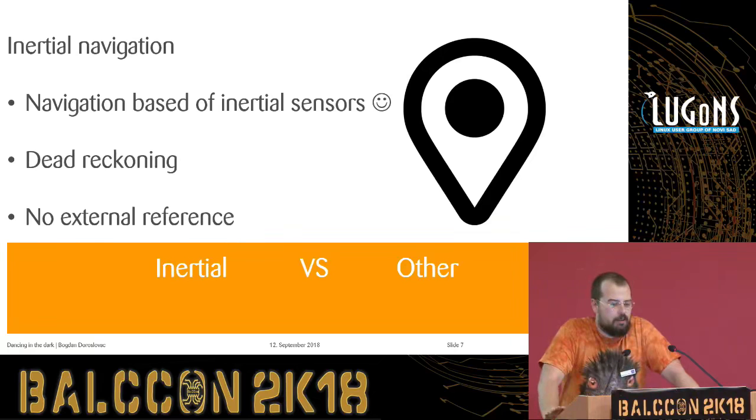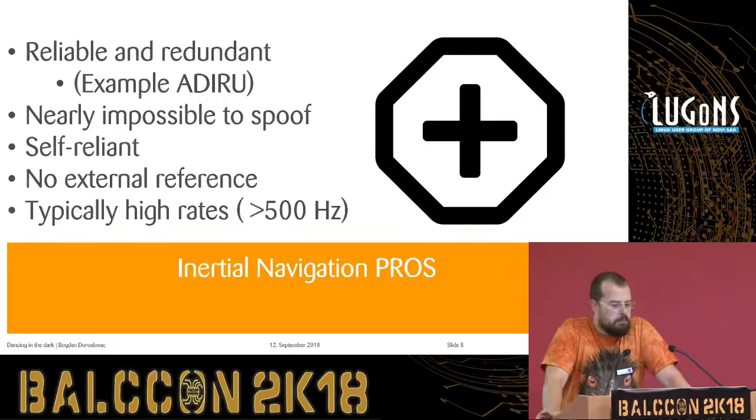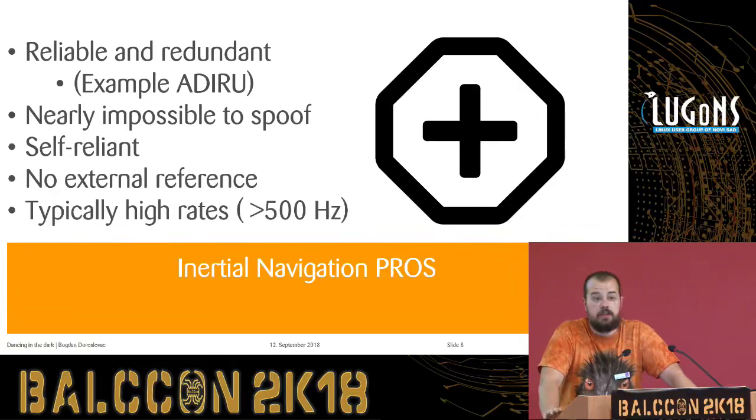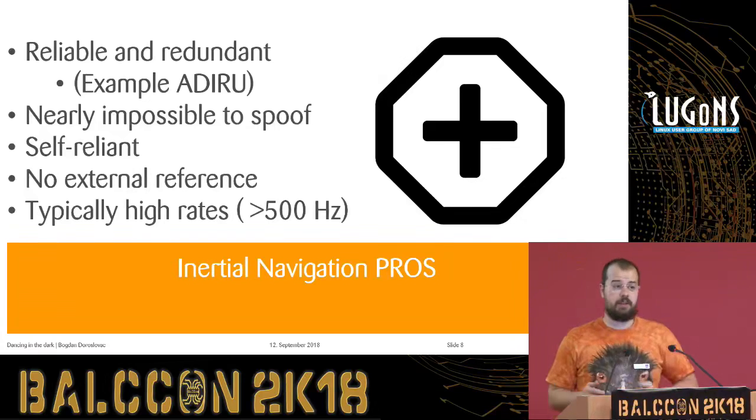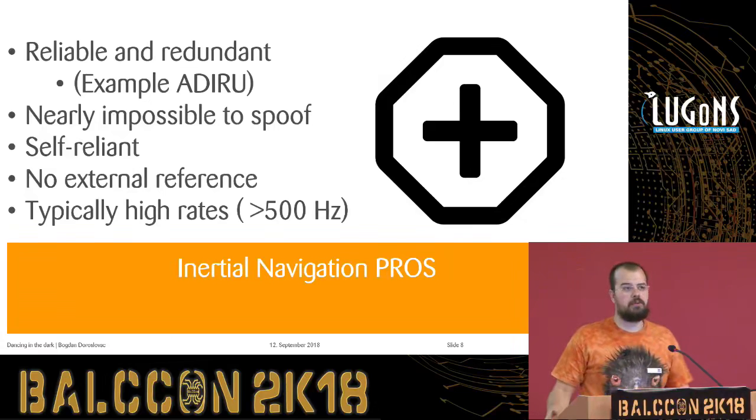And if we're talking about fast-moving vehicles like, let's say, rockets, you have a pretty slim chance of getting to interfere with its GPS. If you're getting it, you have other means of getting it in the first place. So, reliability is the key aspect. Also mentioned in Zoz's lecture yesterday was the aircraft GPS. Typically, let's say Airbus will have what's called an ADIRU, Air Data Inertial Reference Unit, or actually 3 of them, which will correlate and try to find where you are heading, and the error should be slim, up to 0.1%.